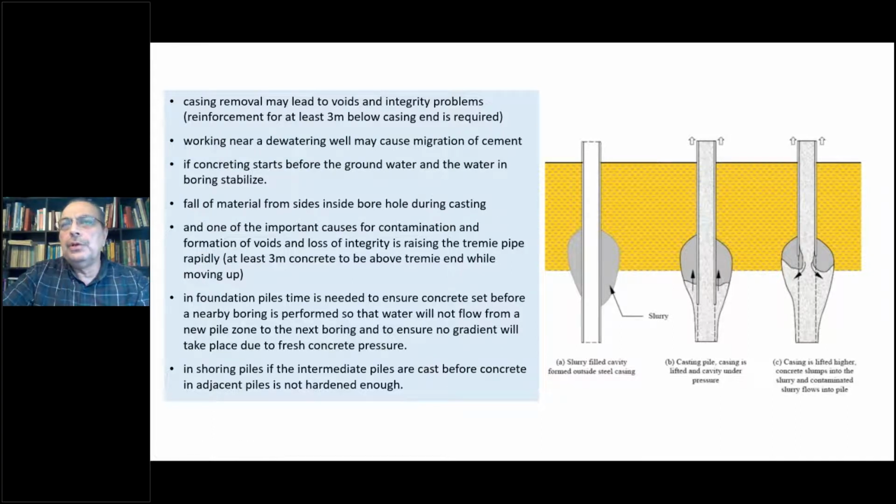So you need to be sure that you don't have collapsing material around the hole. This we encourage every project to have prior to the project start: a trial boring to check how much collapse and how much diameter changes may happen through the length of the drilled hole.